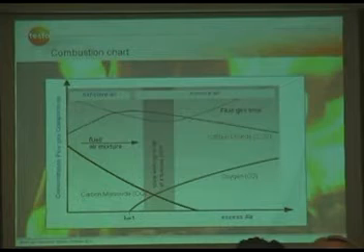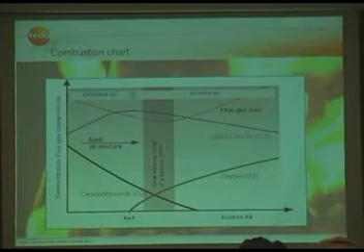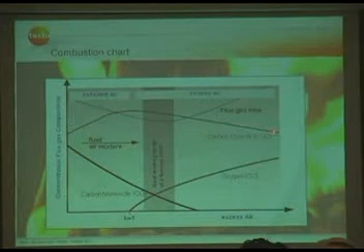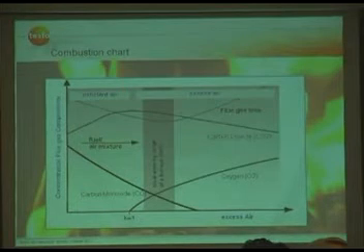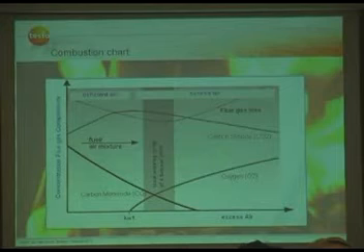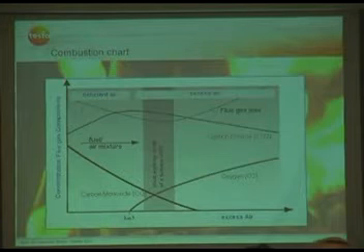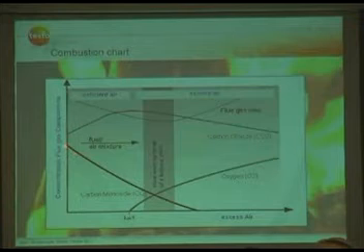Here, this combustion chart shows you the relation between carbon monoxide, CO, oxygen, carbon dioxide, and the flue gas loss. In the left part, where lambda is smaller than 1, we are talking about deficient air. That means there is not enough oxygen present for the combustion. And on the right-hand part, we are talking about excess air. In every combustion process, if you don't have enough oxygen present for the combustion, you will have very high CO readings.